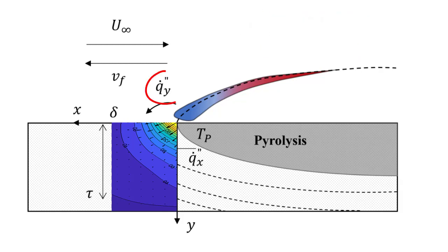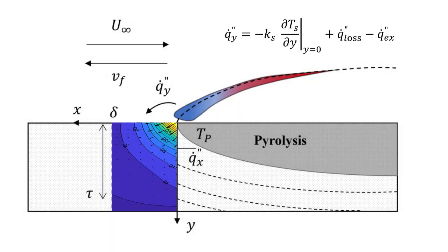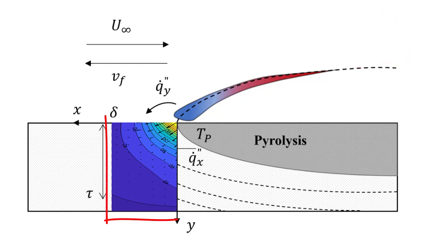Similarly, Qy, or our gas phase heat transfer term, can be found by evaluating the thermal gradient along the surface of the solid. Now, calculating in this way gives you the net heat flux conducted into the solid at the surface. But evaluating this thermal gradient alone does not directly give you the heat flux exposure from the flame. Instead, this is the net heat flux absorbed. In order to calculate the value of Qy, one must also consider other effects such as radiative losses at the surface. These calculation methods effectively take the measured thermal distribution through the solid, as seen in previous work by Ito and Kashiwagi,